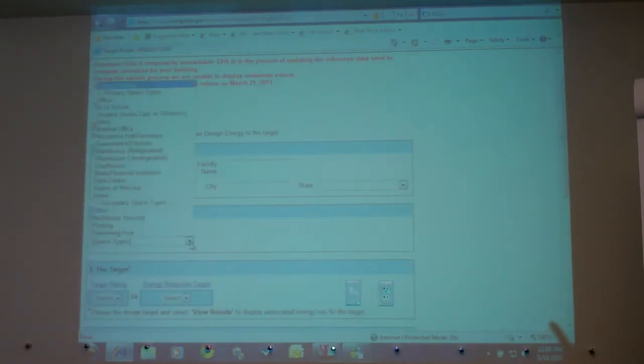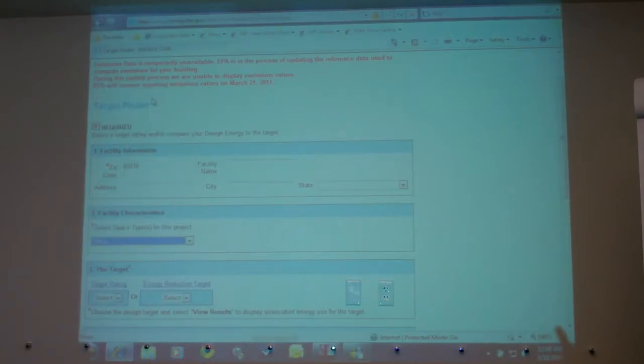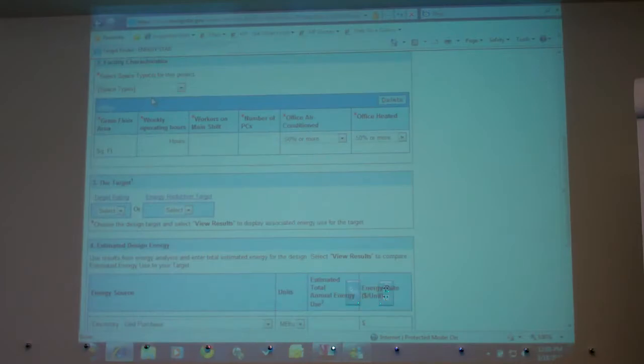On this form, I'm going to do an office building. Does anyone remember what the average EUI for an office building in Phoenix is? 70 to 90. It's 80 to 90. Okay. So we'll see if that's true today. So let's take 20,000 square feet. I told you only need two numbers, right? Zip code and 20,000 square feet.